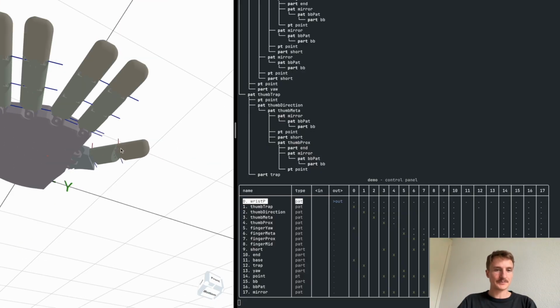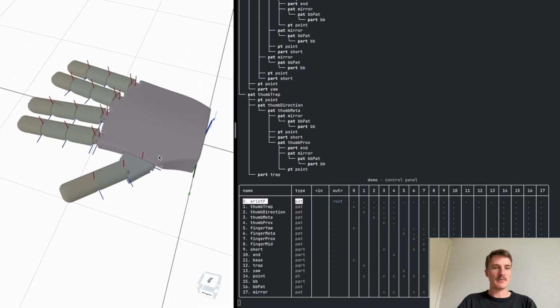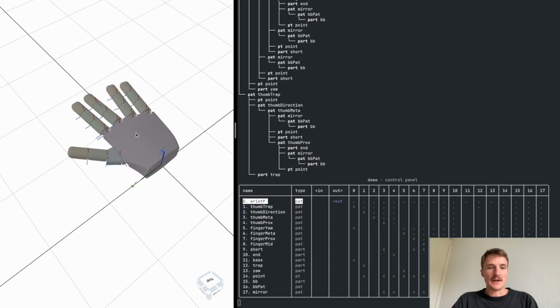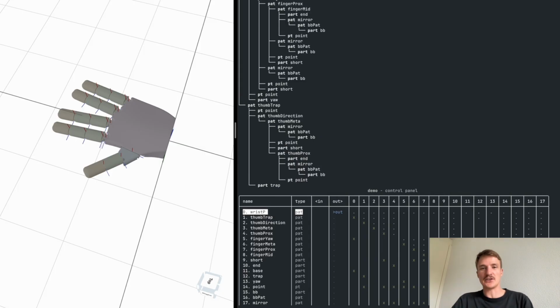and it's also been done on the thumb here. And so I hope you can see that this way we are essentially able to create very stable assemblies where the function actually defines everything. It defines the geometry, defines the point cloud, and it also defines how the assembly is created. Another benefit of using this is that if you have to create many variants of an assembly, it's very easy to do that because you just have to change the settings and the parts that you inject in this tree.